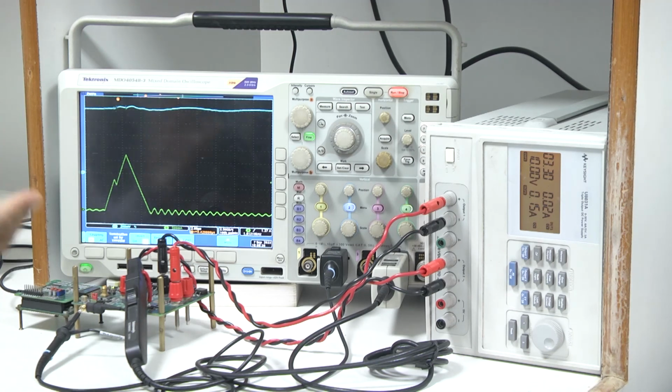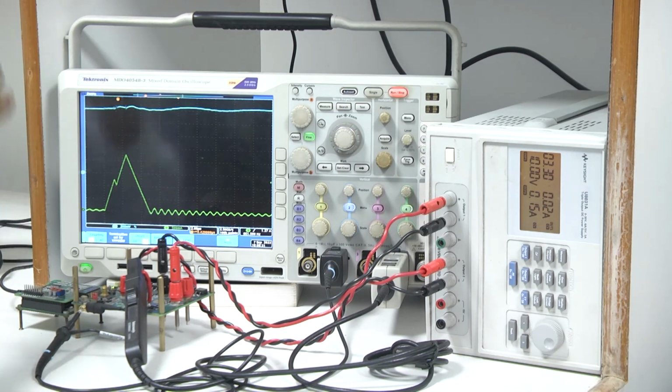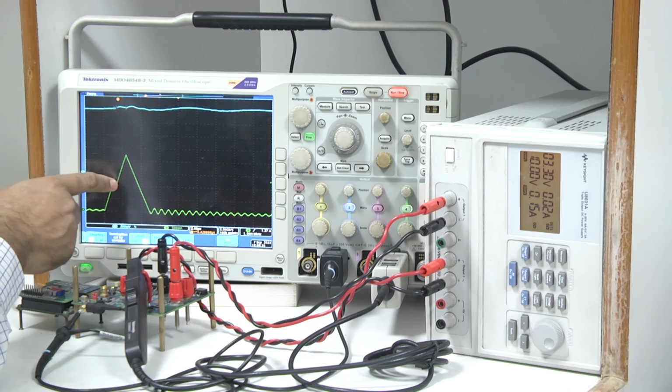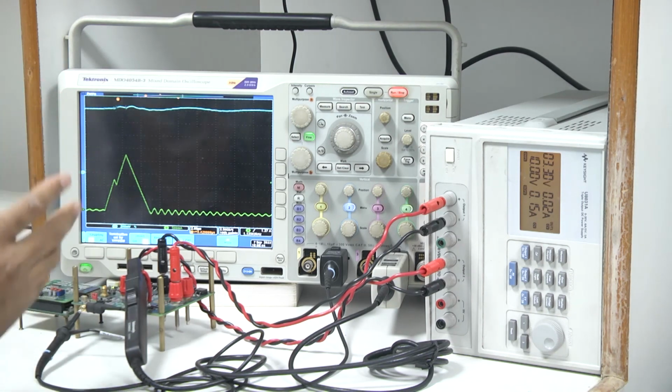We have discussed that we are not taking an analog comparator, we are taking an ADC which is running at a 25 megahertz clock. So naturally there is a time quantization effect, that means a sampling effect, that means we are capturing a sample which shows that it is below reference. That is why it is triggering another on pulse, and in between we have given a minimum off time, which I think is 100 nanosecond or maybe 200 nanosecond.